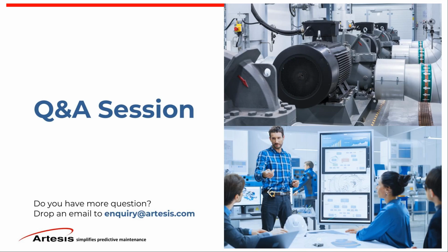So another question is, in case of a 6.6 kilovolt motor, can we connect current and voltage from existing transformers? Yes, you can connect CTs and PTs as long as these CTs are the measurement types, not the protection types. The accuracy there is important. If they are protection type CTs, they are not very accurate. So that would be the limitation there.